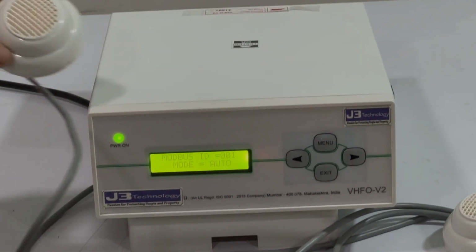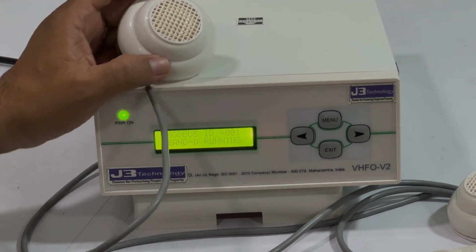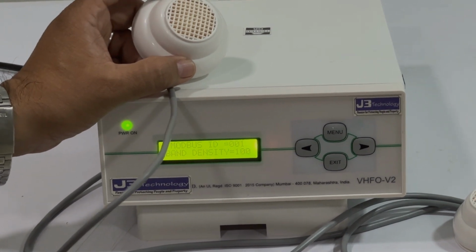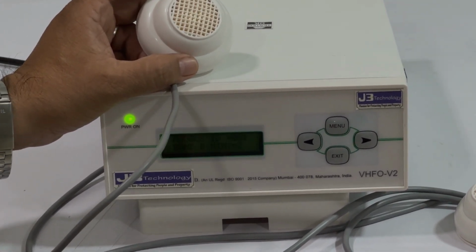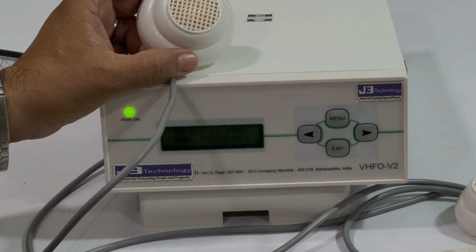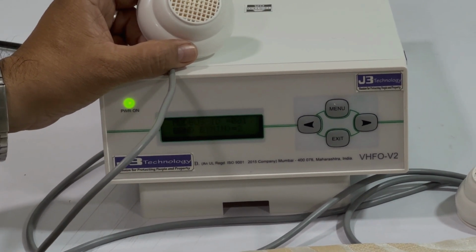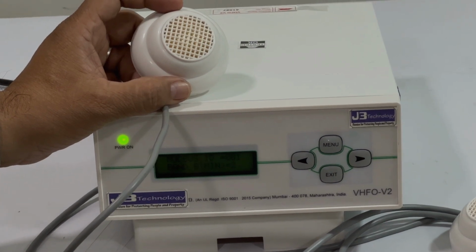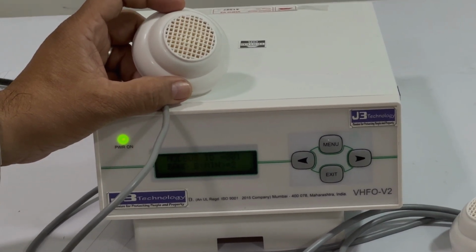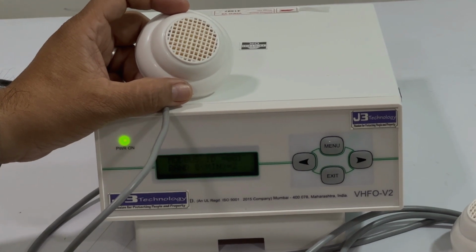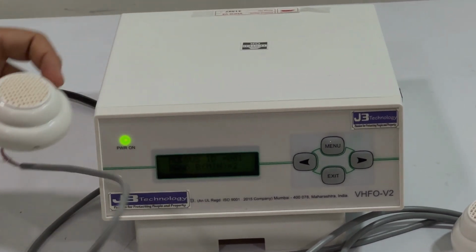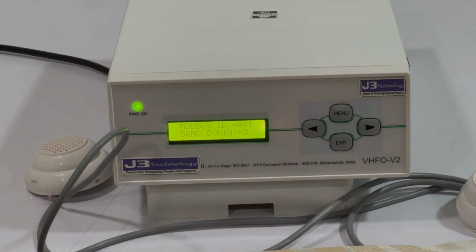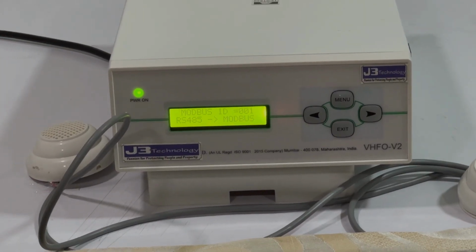And again, if you have a storage rack with a height above 3 feet, you need another transducer; if it's below 3 feet, then it's okay, the sound can cover beyond that storage rack. But if the storage rack is higher than 3 feet, then you have to install one more transducer beyond that storage rack. So for each storage rack, you have to put a transducer. This is the basic thing that I have explained to you.